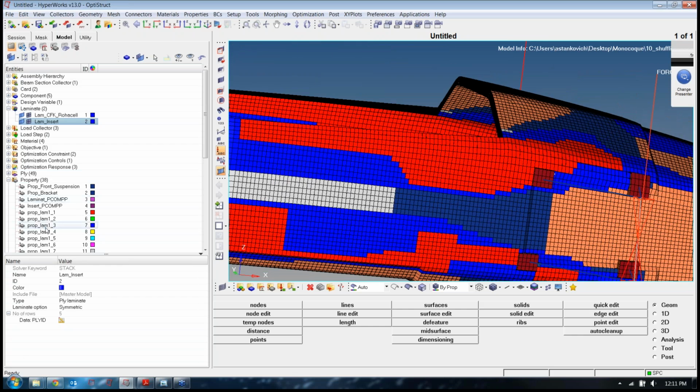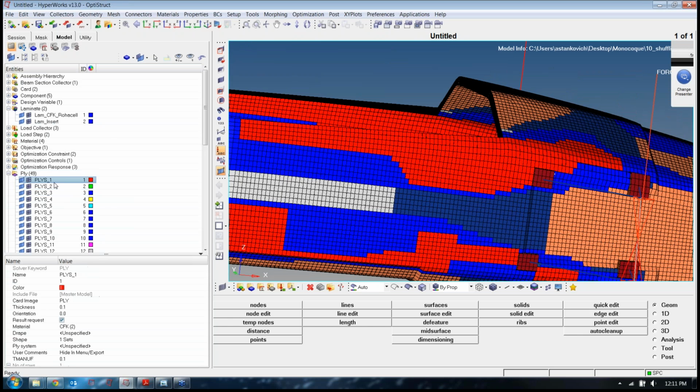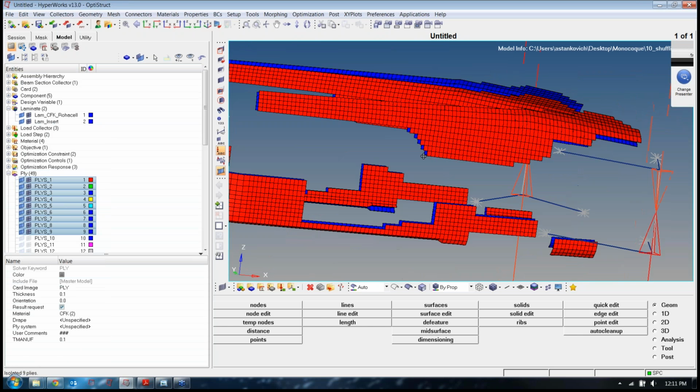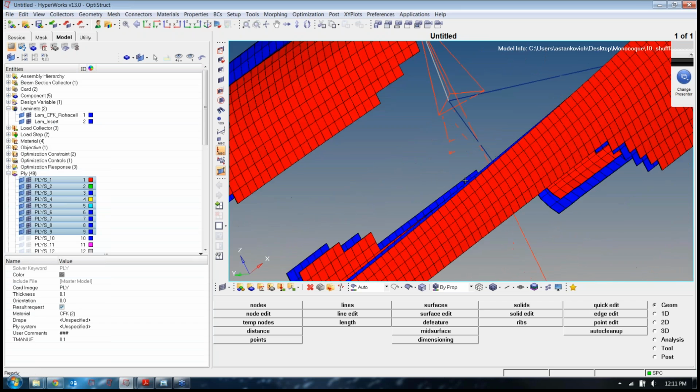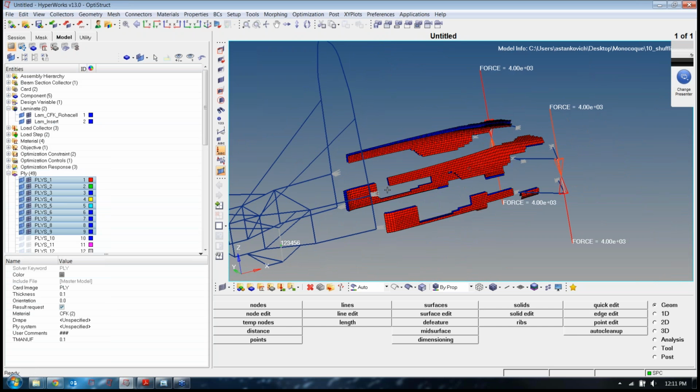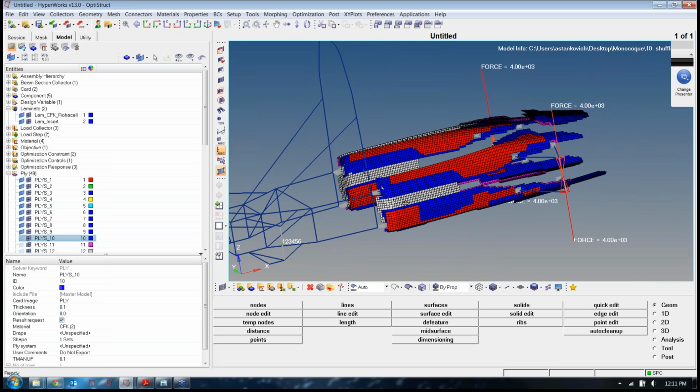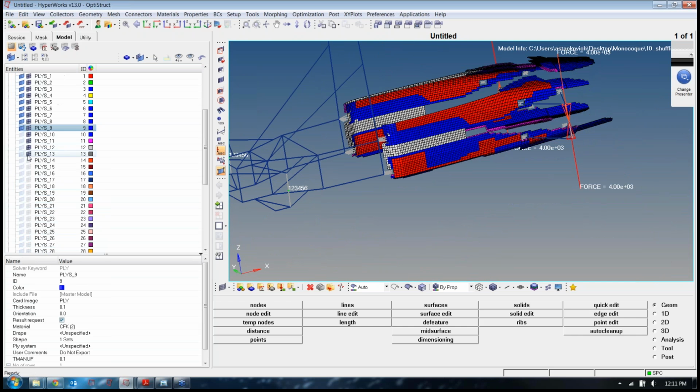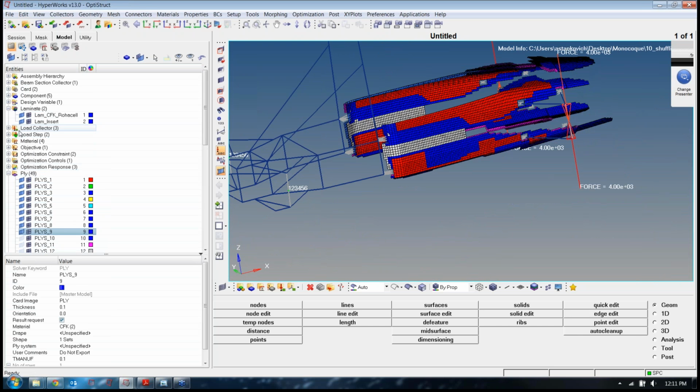And if I go through and start isolating some of these plies, you'll see that these plies have a specific shape, and normally in zone-based modeling, you'd have one zone which represents all of a specific area which has all of the same plies. And so in ply-based modeling, you're basically going through and keeping all the ply entities and just representing one card that kind of defines the entire laminate. And that's called our stack card, and you'll see it here underneath this laminate feature.